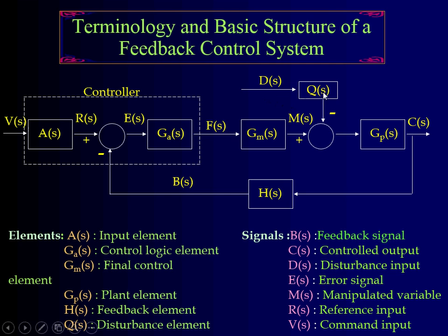This one in here measures the disturbance of the system. For example, if you are trying to control the temperature of a room and somebody opens the door, that would be considered a disturbance. So the disturbance modifies the input to the system and messes it up. So you need to go to the feedback loop, compare it again, and compensate it again until this will adjust. So the H of S is the feedback element.